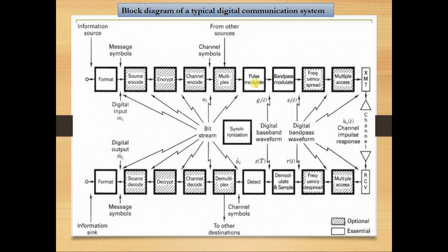So pulse now is the moment where you convert your digital sequence into electrical signal, and you select a pulse that is suitable to protect your data from the impairments caused by the wireless medium or wired medium. And you also choose a pulse that can determine clearly where your data starts, where your data ends, how much time and duration it should take, and which frequency it should occupy. All these details are determined by the pulse.